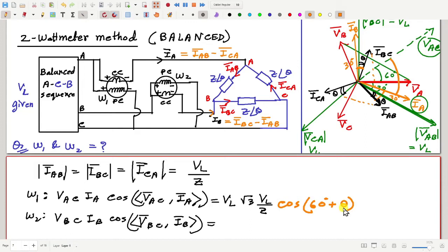Do I have any mistake anywhere? Yes, sir. That green color 60 should be 30 there. Why are you saying that? Because the greens are at 120 with each other. Yes, so this dark green is at minus VC at minus 120, so this dark green is at minus 150. So therefore this is at 30. Yes, you're right. This is 30, so this is also 30.